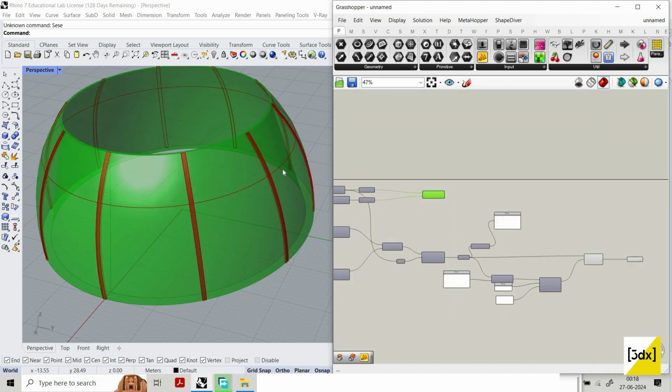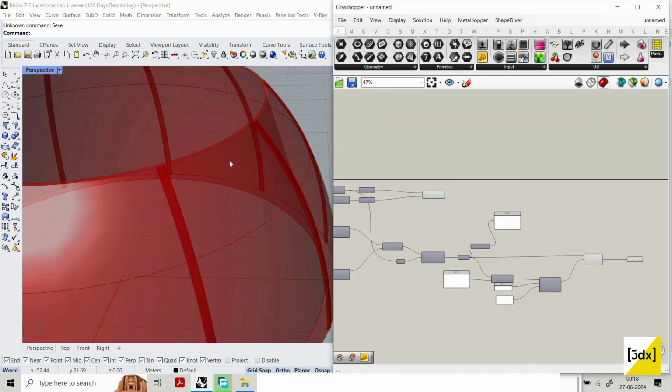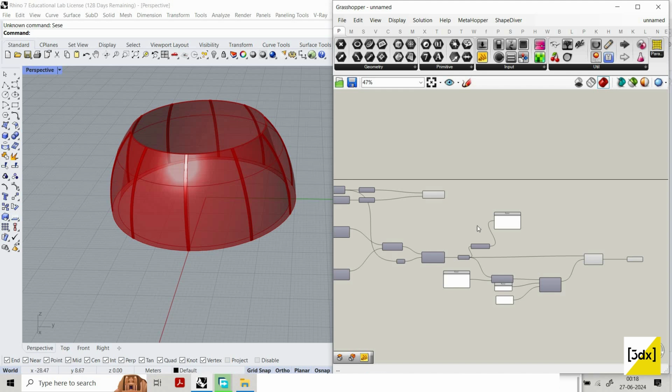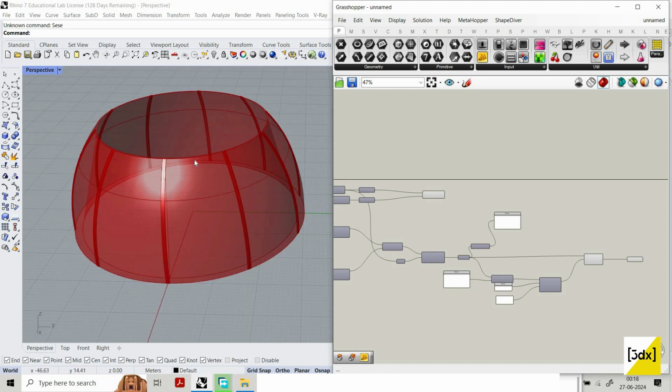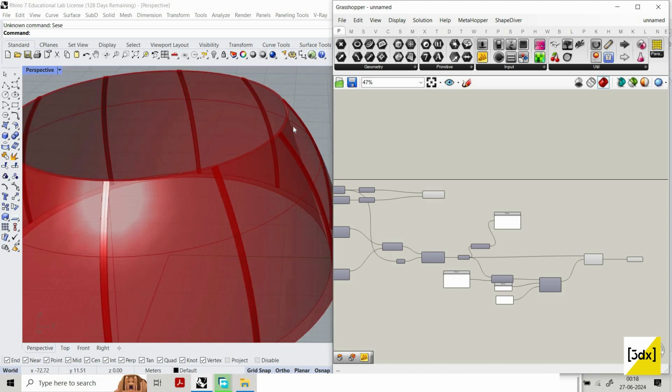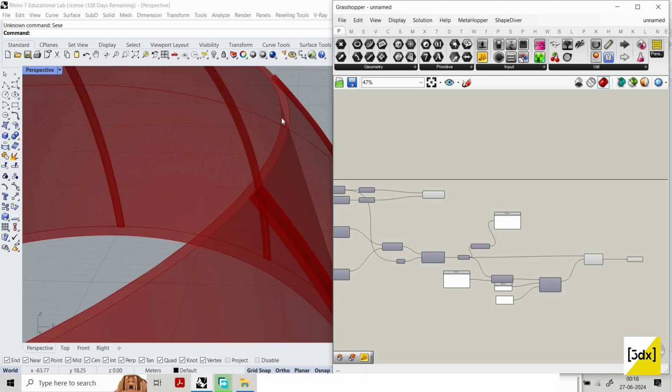So now we've got the inner structure, then we've got the outer frame. Now we want to create a similar top frame. Creating the top frame is so simple. You select these two curves and loft it, or extrude it and then cap it. That is one better way.